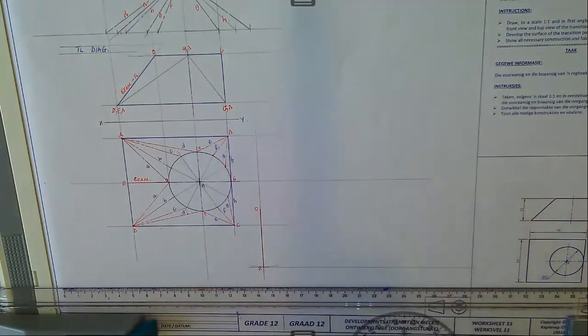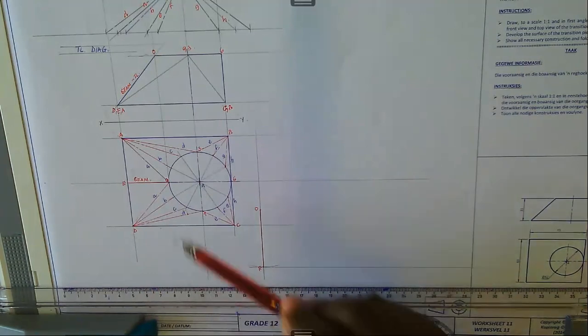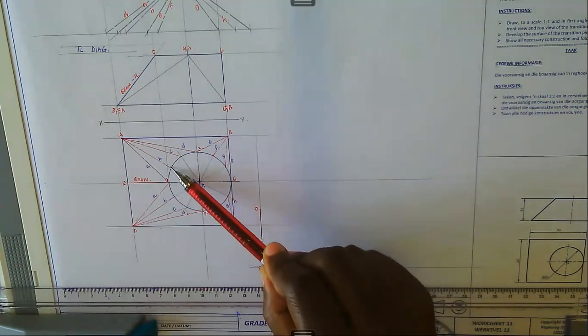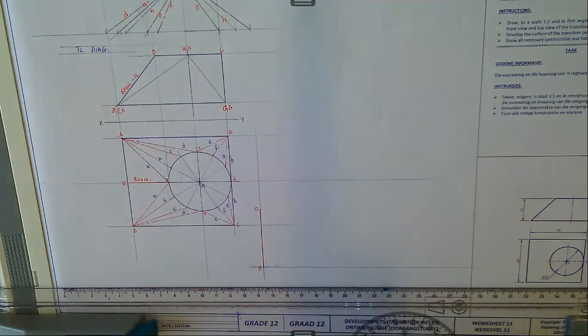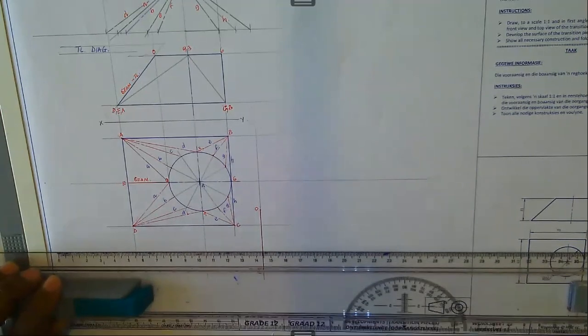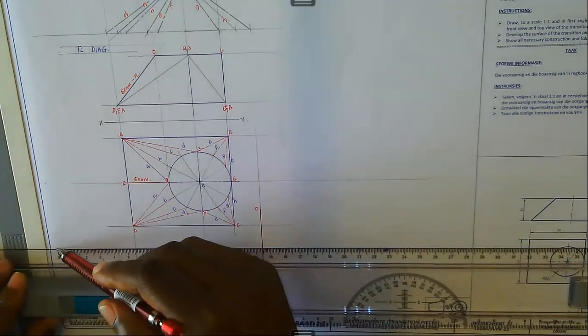Divide it into a number of equal parts. If you want to get the exact size, instead of taking from 0 to 1 like that, we can say the diameter is 42, which is 42 multiplied by pi is equal to 131. So I can draw a line here like that.